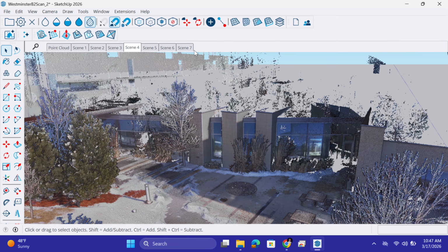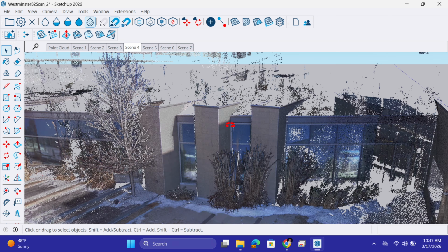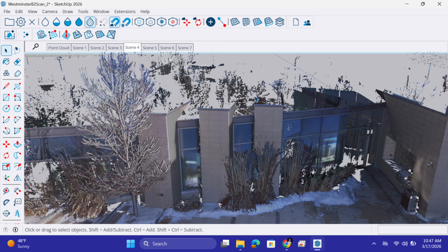So it's a basic laptop, and one of the great things about Scan Essentials is that you're now allowed to, as opposed to constantly snapping to the geometry that's within your model viewer, snap to the points of the actual point cloud, and you can snap to them individually. So for example, let's say we want to start modeling some of these columns here that are in the breezeway.